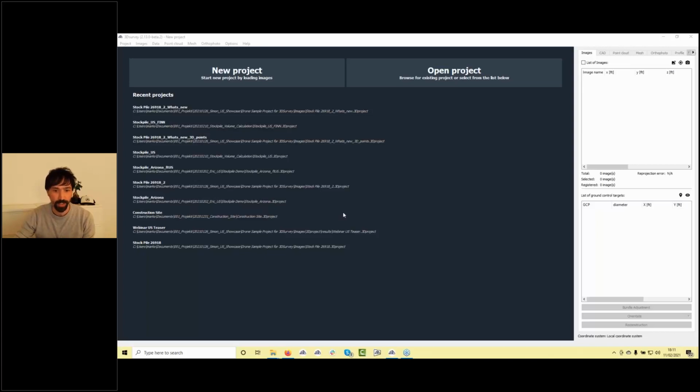Okay, the next question from Benjamin Rabish: How does the classification tool work on a quarry with a lot of vegetation? Works pretty well. The classification in 3D Survey is really easy and effective. I know US customers really like it because in competing software it's more complicated and not so effective. So just try it, and contact our support team if you need help.